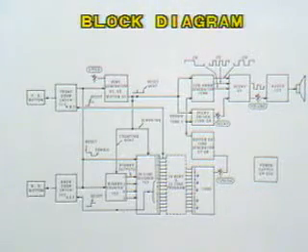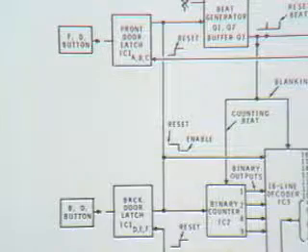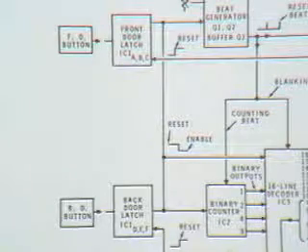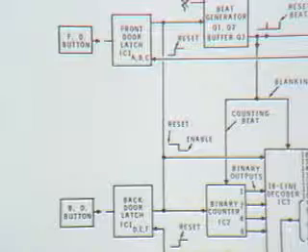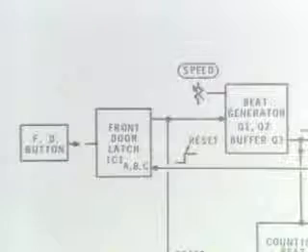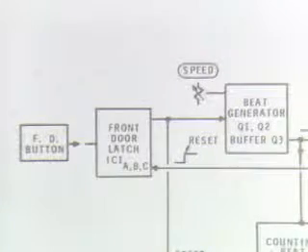First, let's examine the block diagram to get an overview of this circuit's operation before examining subcircuits and devices in more depth. The block diagram is a common tool supplied by manufacturers to give technicians just such an overview. When the push-button switch is pressed on either the front or back door, either of two identical latching circuits composed of IC1 are activated. These latching circuits are built so that the circuits operate for the full 16 beats for which it was designed, and then the latch resets.